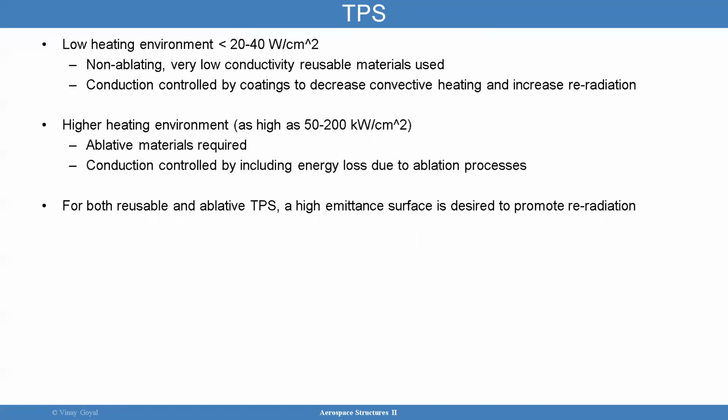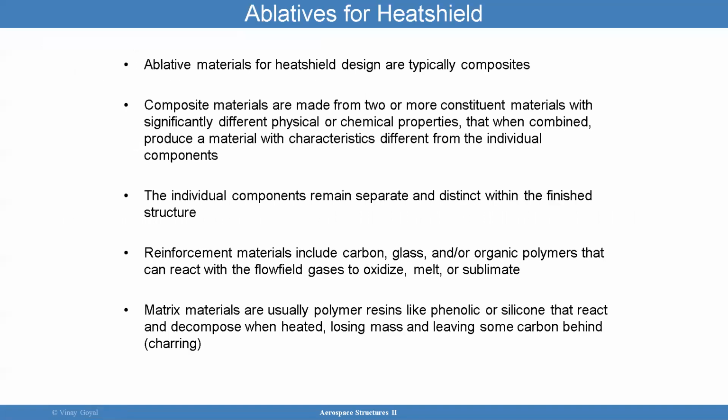For both reusable and ablative TPS, a high emitting surface is desired to promote re-radiation. In other words, you want to have a surface that can emit really well. And you can do that. And that way you can also have heat being removed from the system.